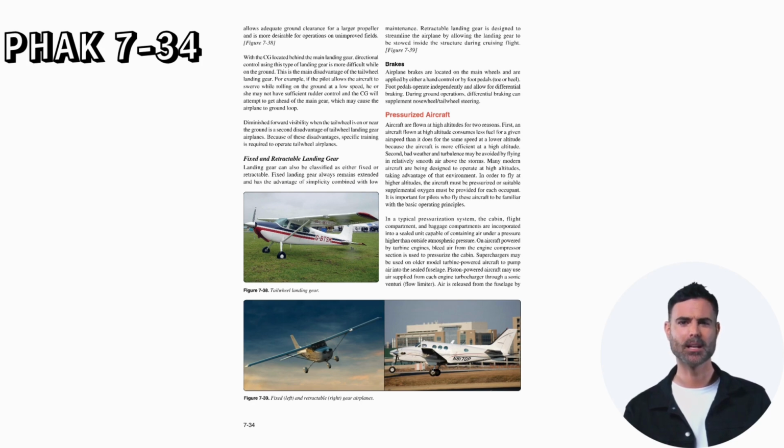Fixed and retractable landing gear can also be classified as either fixed or retractable. Fixed landing gear always remains extended and has the advantage of simplicity combined with low maintenance. Retractable landing gear is designed to streamline the airplane by allowing the landing gear to be stowed inside the structure during cruising flight. Brakes. Airplane brakes are located on the main wheels and are applied by either a hand control or by foot pedals, toe or heel. Foot pedals operate independently and allow for differential braking. During ground operations, differential braking can supplement nose wheel or tail wheel steering.